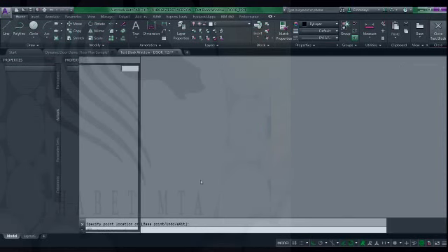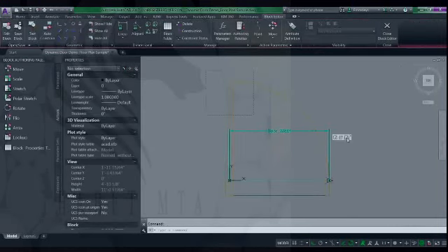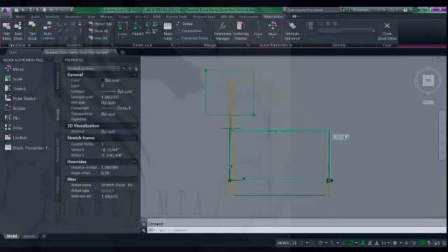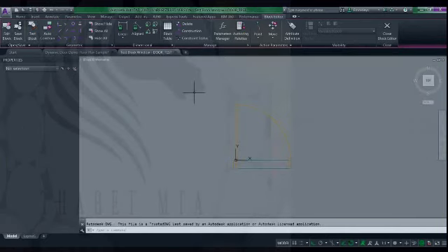So let's get out of here, close our test block, and then we are going to go ahead and select our action stretch for our door panel. Come over to our properties box, our dialog box, and we are going to go to angle offset. And depending on what units you're drawing in, this is going to vary. But for me, 90 angle offset is going to work. Let's test it to see.